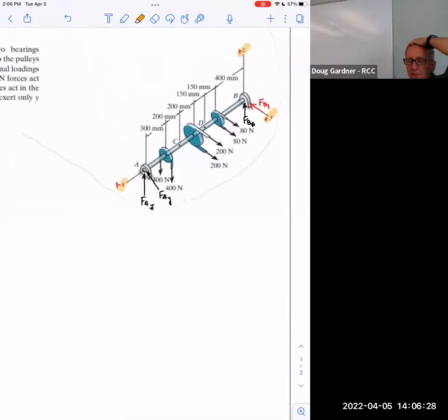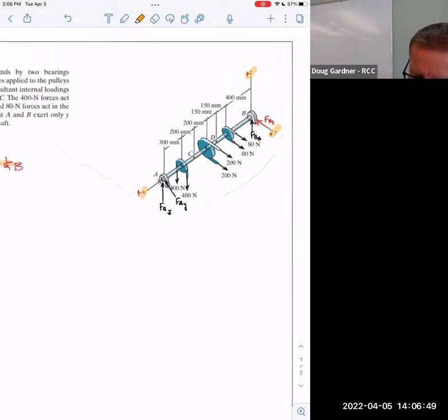And so the only advice I would give you with these is make sure you're really careful to draw your lines correctly parallel. Like Z is straight up, and so I was careful to draw force of AZ and force of BZ straight up. And then I tried to draw force of AY and force of BY parallel to the y-axis, because you're trying to draw 3D here, and it's just not going to work so good.